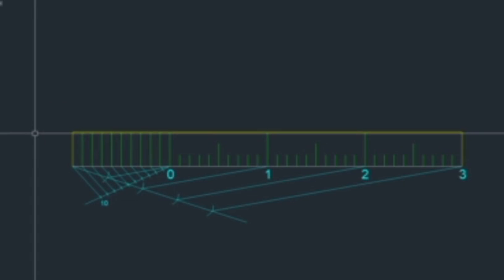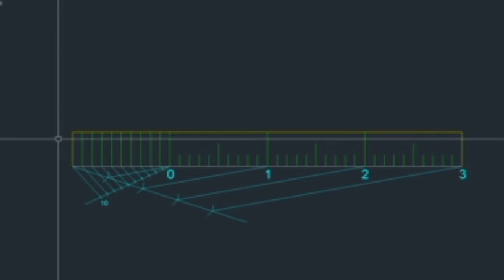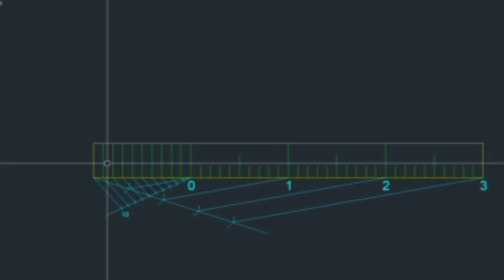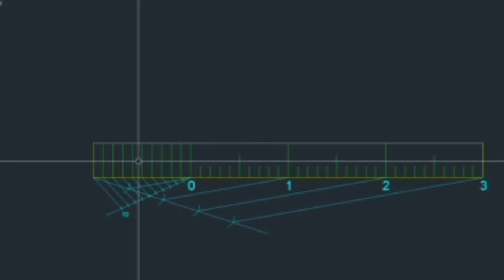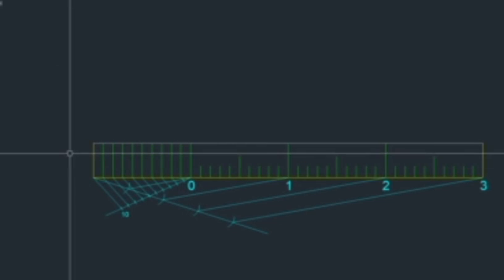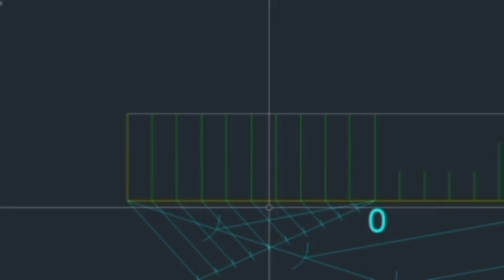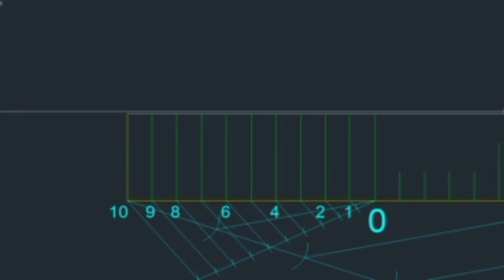So here I told you retrograde for backward reading, or direct for forward reading. So this drawing I will make into a retrograde drawing. Retrograde means what? Here in the main scale I am taking 10 divisions plus 1. So assume this is the n. I'm taking one division here, n plus 1. So from here to here is 10 divisions. I'm taking one more division.